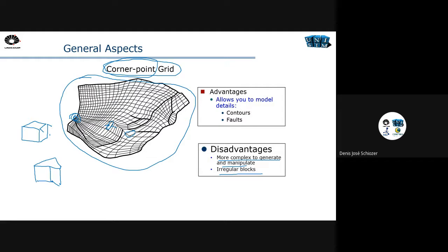And remember that we are discretizing in space here, but also in time. So we have to advance in time. As you can see, our numerical technique will advance in time according to the estimated errors for the next time step. So for bigger blocks, this time step can be big. But for smaller blocks, as I'm going to show in the equations, the simulation requires smaller time steps. So let's assume, for example, that I have to simulate 20 years, and I'm simulating from month to month,